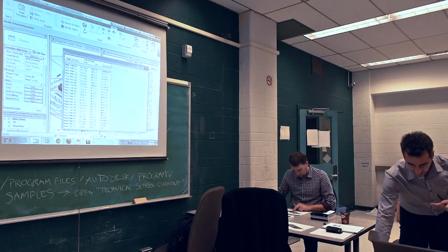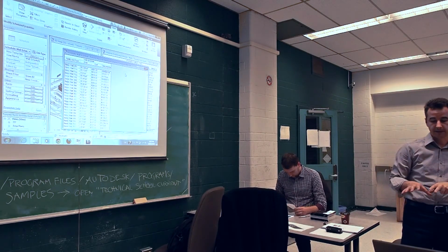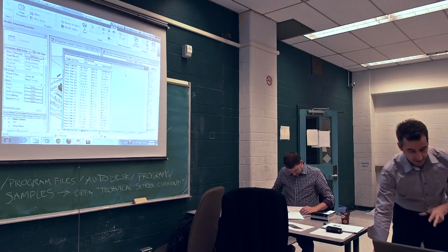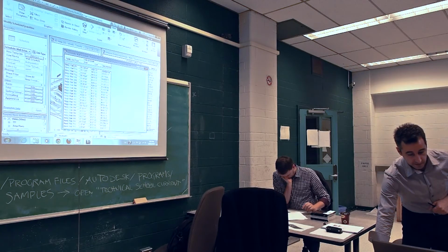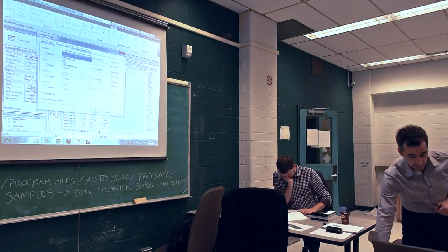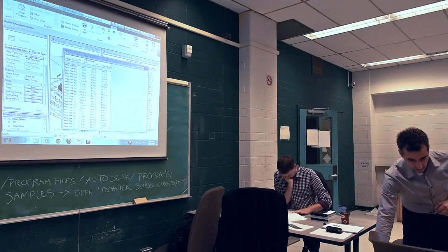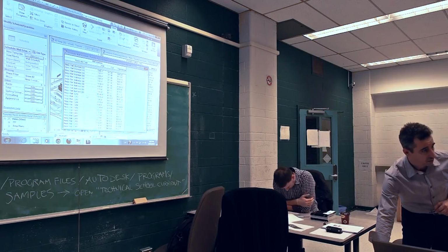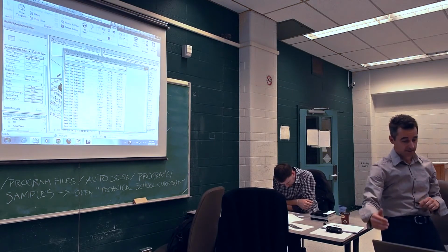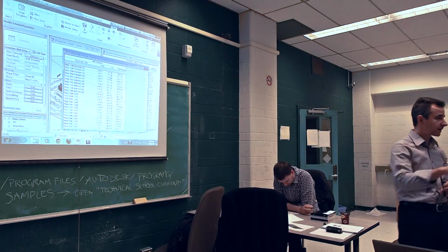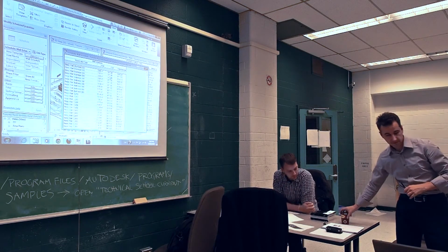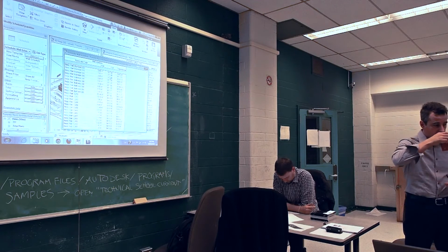So obviously I have most of the stuff that I need, but it's not final. I have to edit this, right? I have to keep working. So in the sorting grouping, I would like to sort by family and type. Yeah. So let's do that. Now everything is grouped. At this point you have the areas and you can add some cost. I would actually say add some cost in the schedule, see how that works.